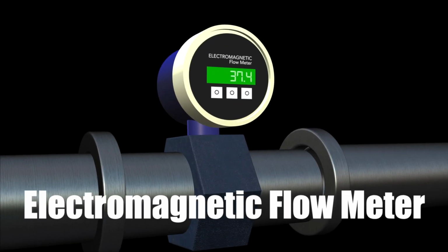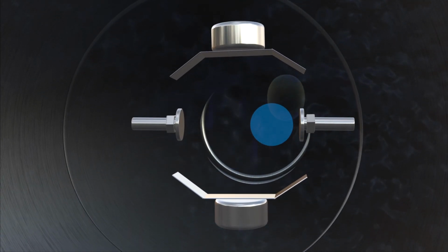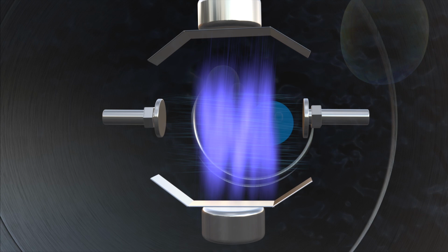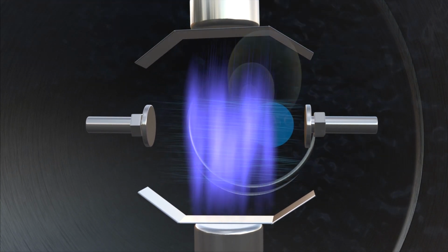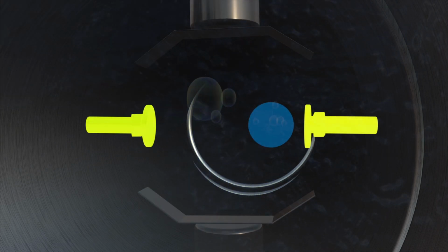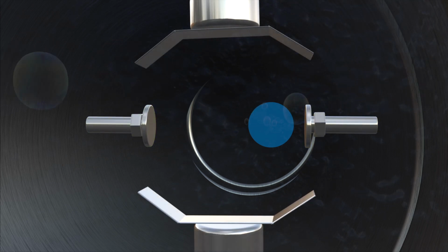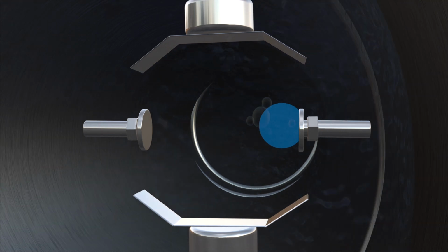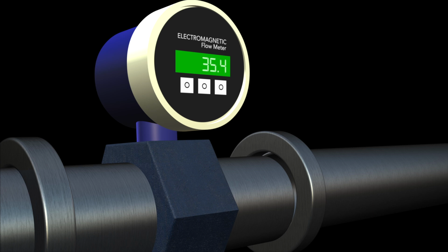Electromagnetic meters are an electronic flow meter, often called the mag meter. A magnetic field is generated and channeled into the water flowing through the pipe. The flow of conductive water through the magnetic field will cause a voltage signal to be sensed by the electrodes located on the pipe walls. When the water moves faster, more voltage is generated. The voltage generated is proportional to the flow of the water. Electromagnetic water meters should not be used on systems with low conductivity water.